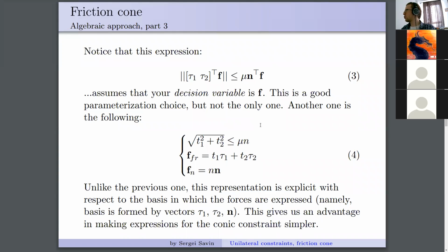Okay, so the friction cone entirely depends on mu. Mu is the only thing that describes the friction cone. If mu is small, then the friction cone is narrow. If mu is big, the friction cone is wide. That's all. Because mu is equal to, wait a second, let me not make any mistake. Arctangent of mu is the angle of the friction cone.